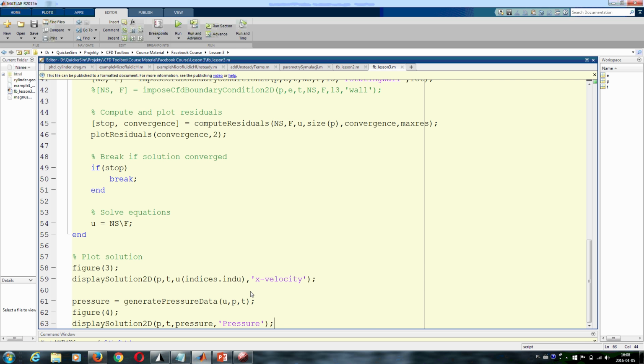Well, you might be bothered, where did we specify fluid density? Well, we didn't, because we are dealing with an incompressible flow, so you can divide your Navier-Stokes equations by density, and the only difference is that the pressure you get from the simulation is pressure divided by density. So if you would like to have real pressure in pascals, you should multiply this pressure by the density of the fluid you deal with.